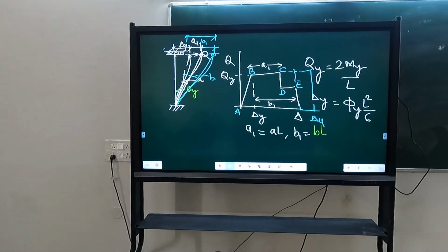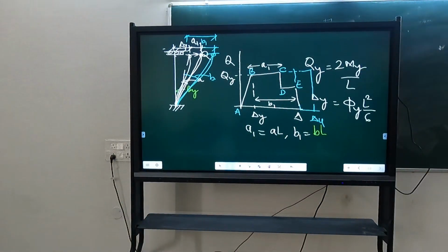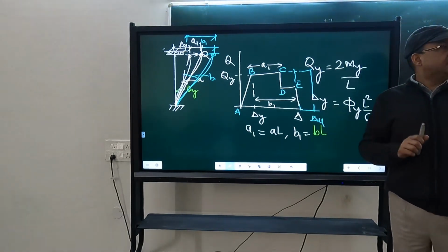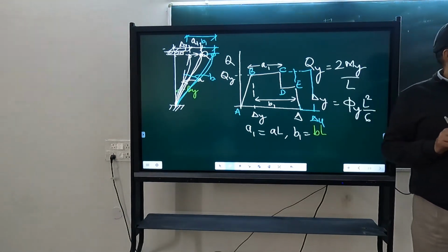You have seen under cyclic load, in the first initial lectures, we discussed that if it is subjected to cyclic load, it will fail at lower strain. So under cyclic load, our steel is going to fail at lower strain. If you are doing monotonic analysis, then you will predict high, because there we are not considering cyclic loads.